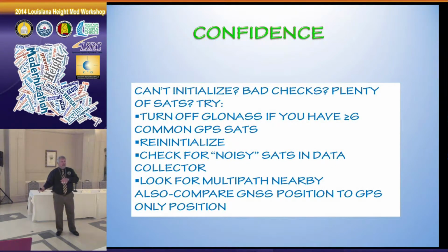Sometimes it gets funky, all right? If you have trouble initializing and you're using GLONASS, turn it off and just do GPS. If you're having noisy solutions, turn it off and just use GPS, if you can. And you can compare each way, you know. But I'd recommend it if you have problems with GLONASS.